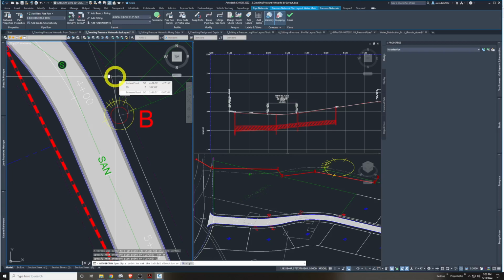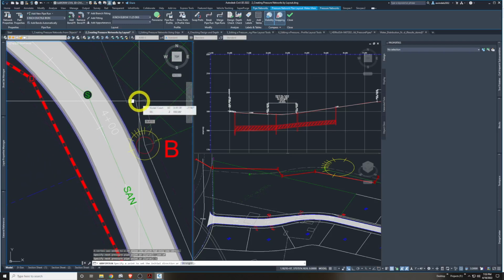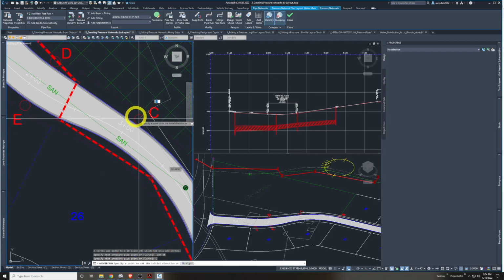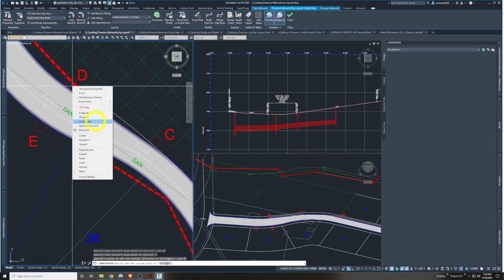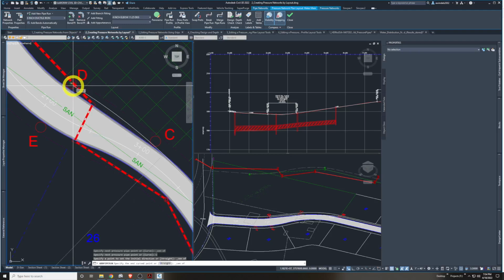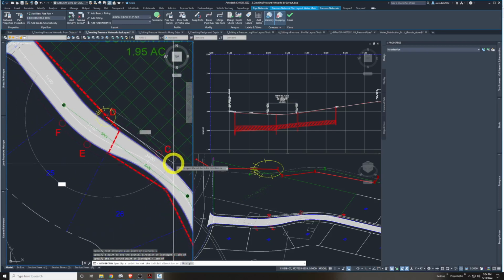And at this point, it wants you to click straight to apply the straight option, snap to the center marked C first. Let's go to center. And now snap to the center marked D, because it's asking where's the end of this curve going to go. We're now telling it to go to D. Let's go there. Curves through D. Okay. See, we made a bit of a curve through there.